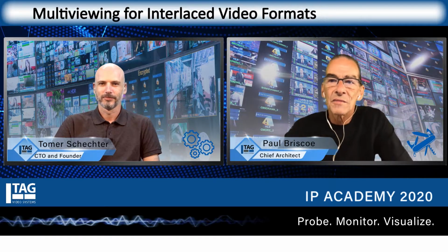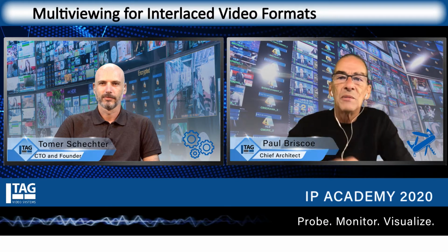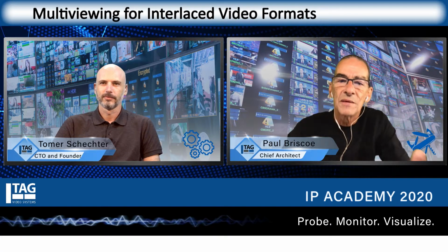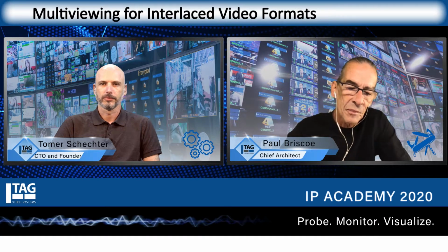In the very earliest days of television, television was a very, very simple system. It basically consisted of scanning an image in a progressive manner. That is, one line at a time, the image would be scanned, and a little tiny electron beam would scan a photosensitive target and develop an electrical voltage corresponding to the light on the target. This was the way the picture was encoded electronically. Then elsewhere, a receiving device would replicate that same scanning pattern, but instead of converting light to electricity, it would take in the electrical signal it received and turn it back into light on the screen and paint that picture back onto a screen. The basic theory, I think everyone knows about television.